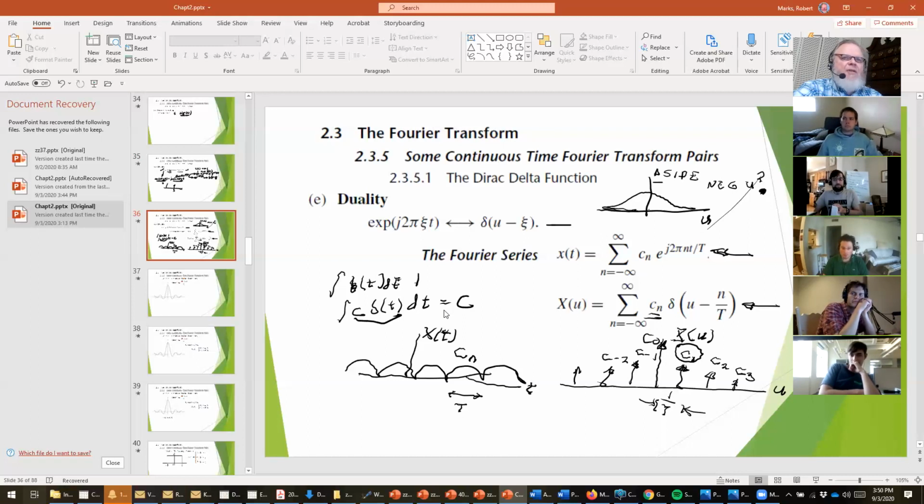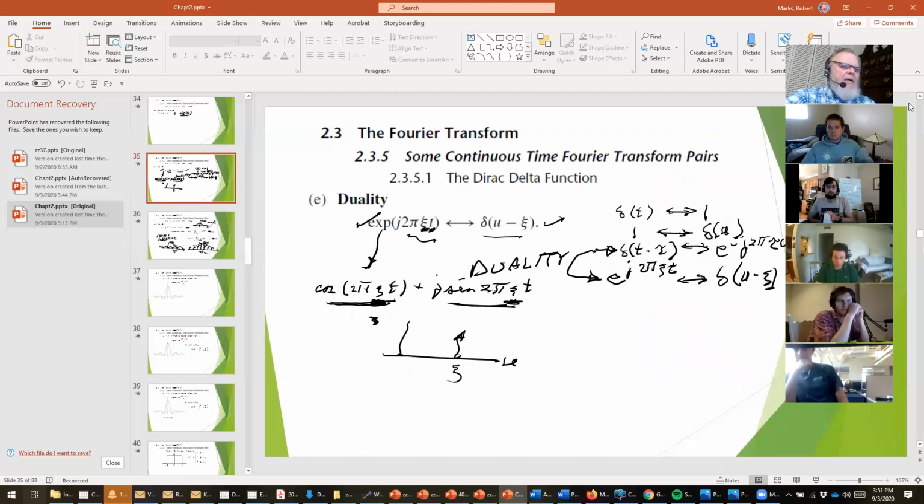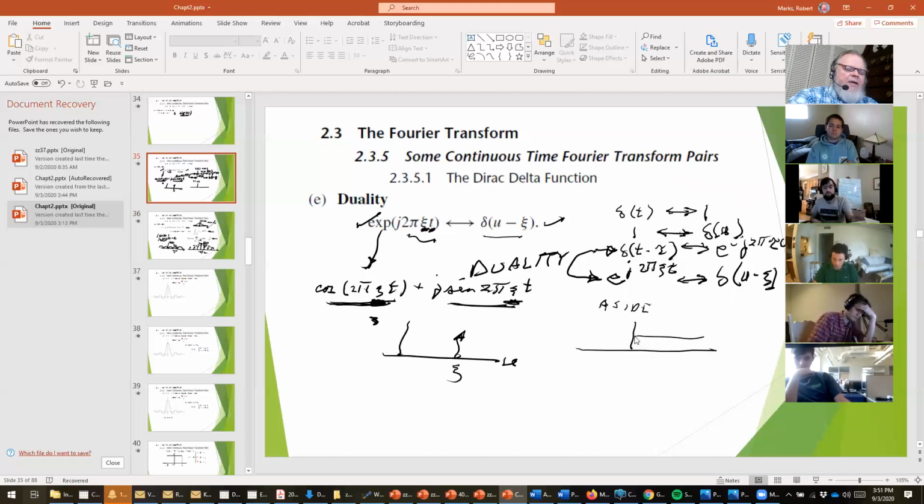It's a wonderful bookkeeping sort of technique, recognizing that we can use these delta functions very nicely in terms of mathematics. Many times, well, here's another property. I'm sorry, I had about 2 or 3 thoughts going through my head. Here's another thought about the Dirac delta. This is kind of a side. Many times we like to talk about the step response, or a unit step function. We haven't defined this yet, but a unit step function is something which is 0 for negative time and 1 for positive time. And we can talk about the derivative of the unit step.